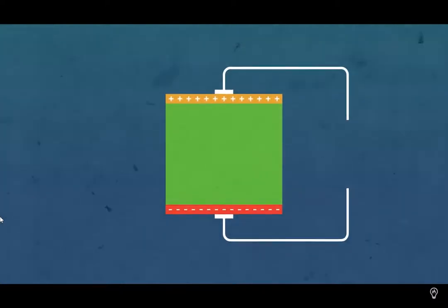But when you compress the crystal, the negative charges shift in one direction and the positive charges shift in the other direction. In the bulk of the crystal, it's still neutral overall. But at the faces, you've got this buildup of positive and negative charge. If you then wire up these faces, well, the positively charged face will be trying to pull electrons towards it from inside the wire, and the negatively charged face will be repelling electrons. And if you bring the ends of those wires close enough together, the electricity will be able to jump the gap, producing a spark.